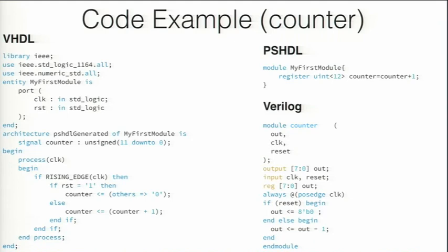There's also Verilog, which sounds like VHDL. Oh, by the way, VHDL was not invented for programming FPGAs, but for documenting ASICs. At one point they thought, if we are putting in all the effort of describing it, why shouldn't we simulate it? So they used VHDL for simulation. And then they realized that if we are simulating it, we can actually use it for synthesis, to put it on an FPGA or on the ASIC.